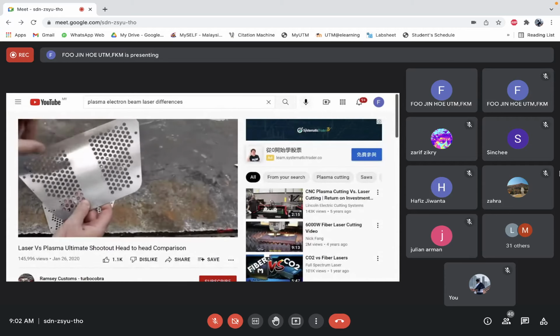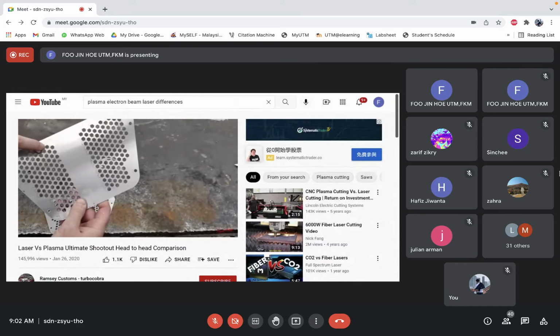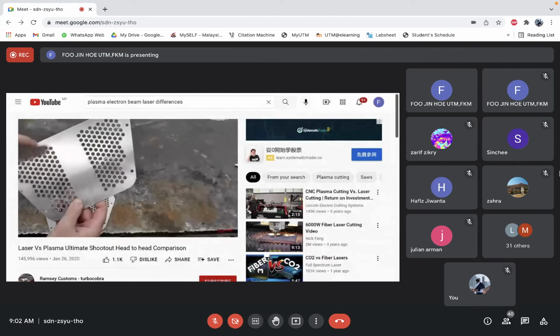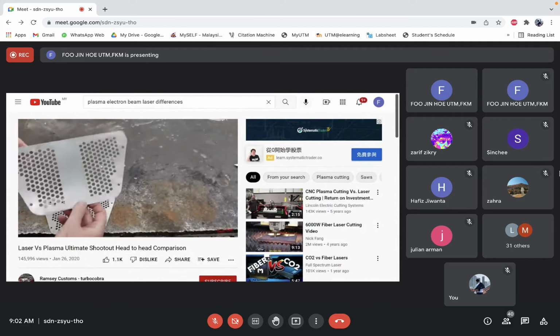Also, I did not do a lead in on any of this, so you can barely see the pierce on each one. So I probably shouldn't run a lead in when I do these as a production run.